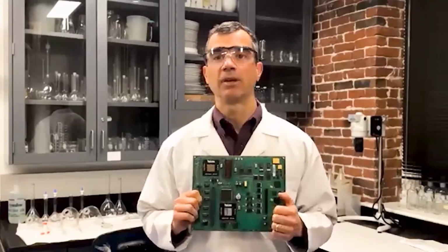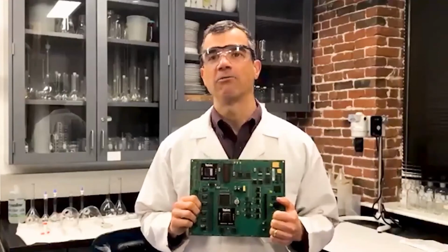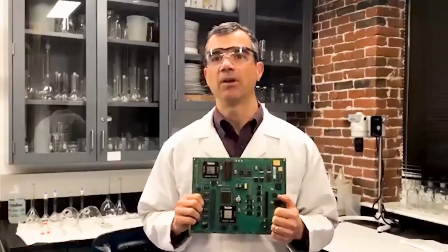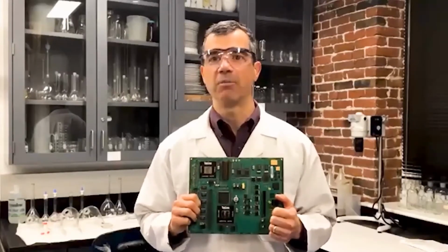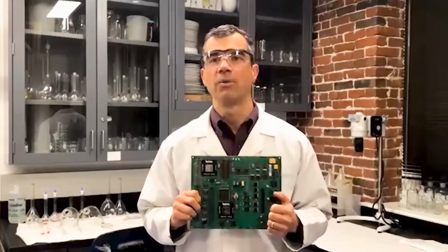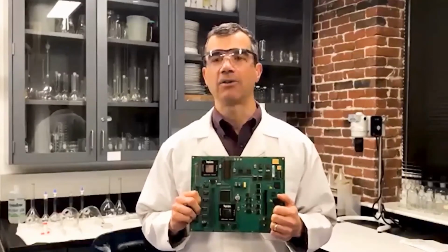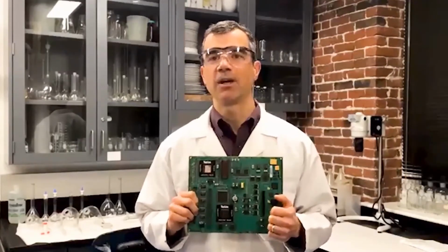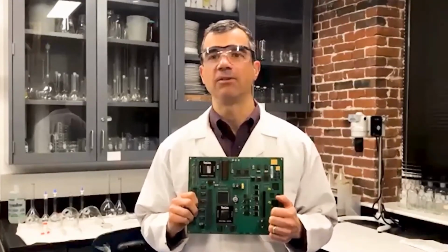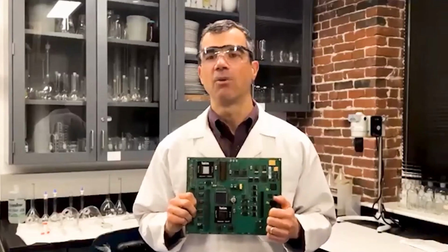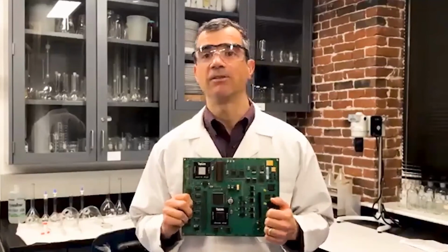And what we're trying to demonstrate here is that this single test vehicle encompassed a wide range of different component types so that we could validate that the lead-free solders would work with a variety of components. So on this single board, we have through-hole components, we have surface mount components, we have connectors, we've got ball grid arrays, we've got a wide variety of component sizes and shapes and geometries and different component finishes. So with one single test vehicle, we're able to accomplish testing for all these different types.